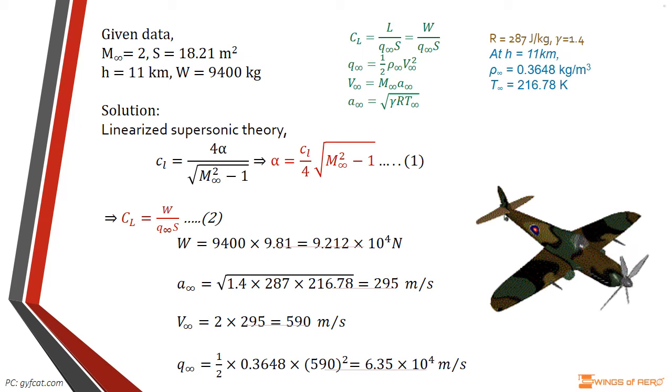At Mach 2, the semi-vertex angle of the Mach cone is mu, equal to sine inverse of 1/2, which is 30 degrees. Therefore, much of the wing is unaffected by the tip effects and experiences two-dimensional flow. The airfoil section of the F-104 is thin and is at a small angle of attack. We conclude that linearized theory should be a good approximation for the lift coefficient of the wing of the F-104. Thus, we use small c suffix L equal to capital C suffix L.